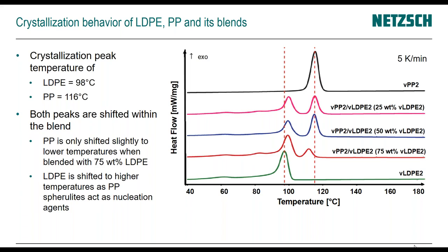The mechanical shredding does not really always cut the molecular chains in the middle, because you have to think of it as really this entangled mess of long molecular chains, and the probability of cutting one of those in half is just lower. But the thermal stress that acts on it, that can have that effect of degradation that leads to molecular chain reduction.